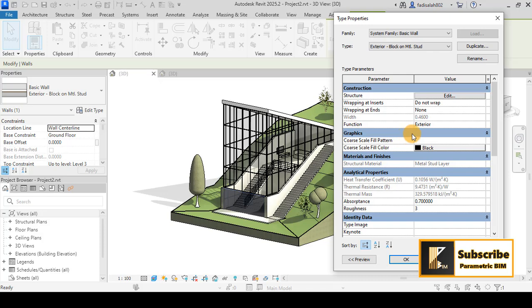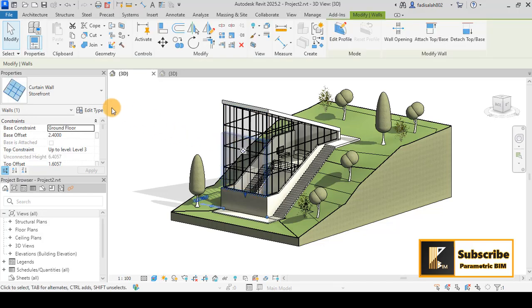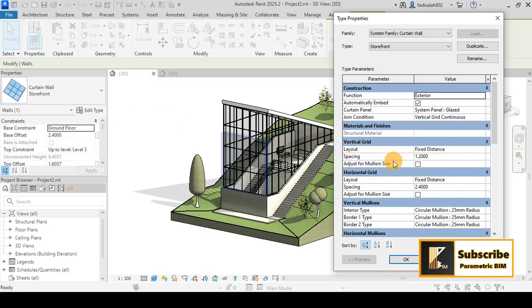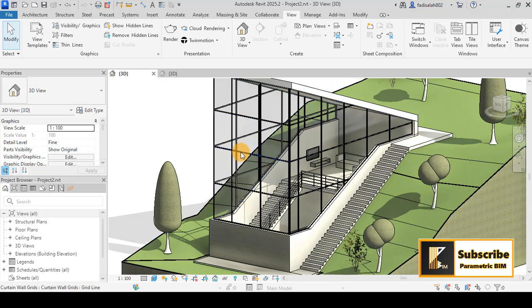So let's take an example here. If I select this curtain wall and come here to edit type, and for example the spacing between these mullions, maybe I change it for the vertical grid to 2 meter, or let's say 2.4, like the horizontal spacing, and apply it, you can see that this property will change all the spacing for all the type, not just for the selected wall.